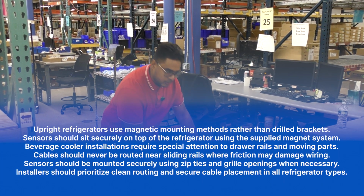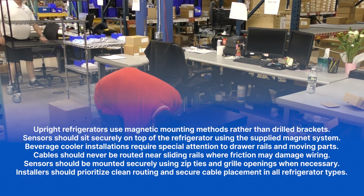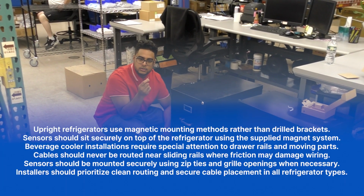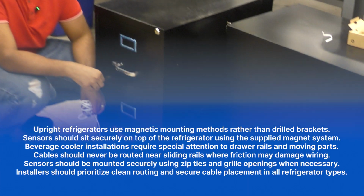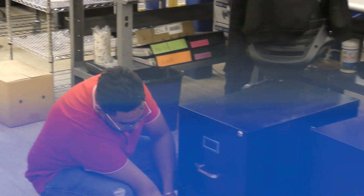Cables should never be routed near sliding rails where friction may damage wiring. Sensors should be mounted securely using zip ties and grill openings when necessary. Installers should prioritize clean routing and secure cable placement in all refrigerator types.